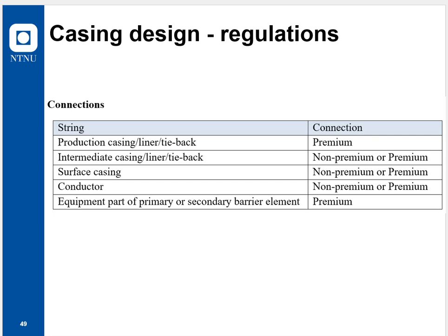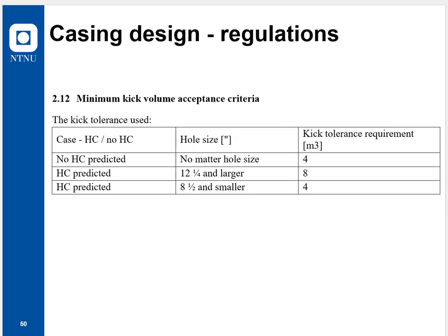I am not going to go into detail for testing of equipment, but what you'll find is that it's from level 1 to level 6, meaning level 6 is vibrations and temperature cycles in combination with gas. I think level 3 is just pressure testing with liquid. That being said, we'll touch upon pressure testing later on, and I will talk more about it then.